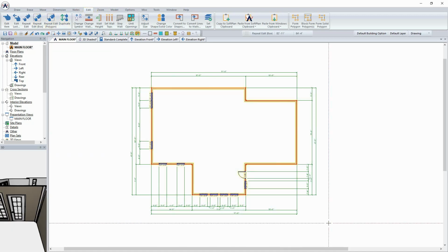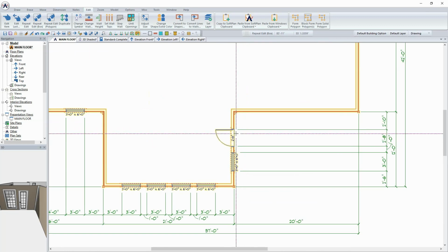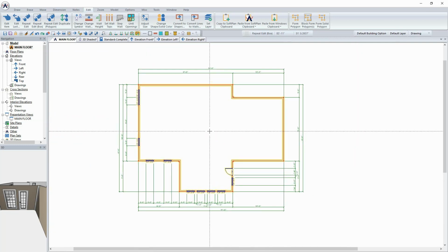I'm just going to sketch a box completely around the plan. Even though the walls were already defined not to include in the soft list, I'm just not going to take a chance and miss anything, so I get all of the openings. They're no longer included in the soft list. Now, obviously, if you were replacing a door, perhaps going out to the outside, you would leave that door in the soft list so that it doesn't calculate. But that basically clears us up there. I'm going to do a cleanup and a save.